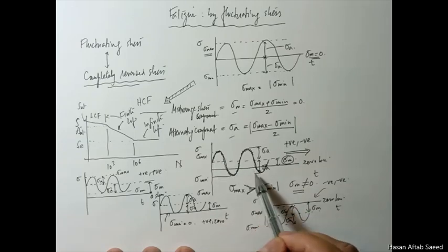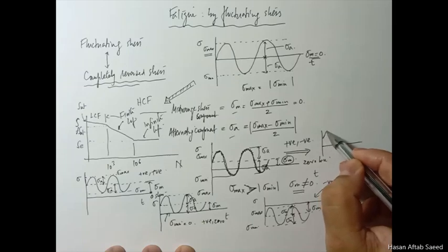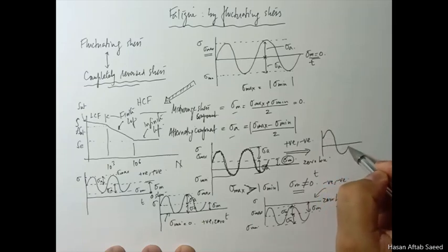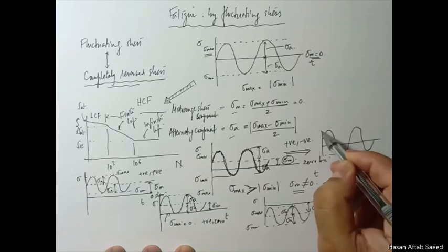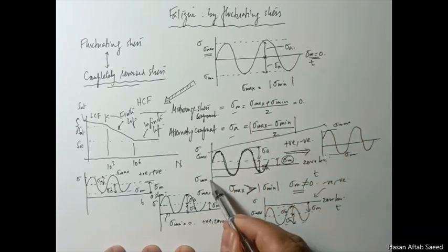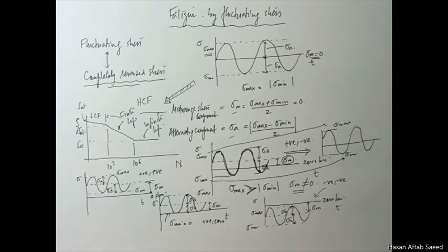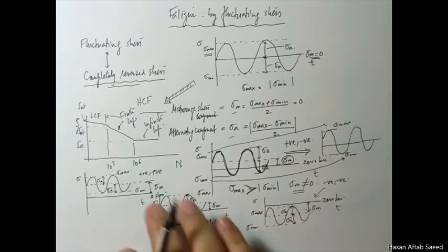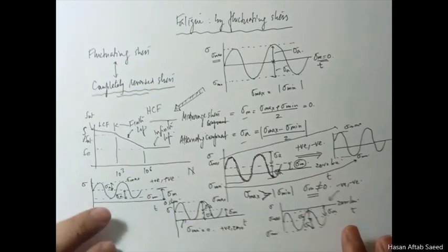Now this sort of thing can very easily be handled by simply taking a simple sinusoidal wave, provided your sigma min and your sigma max are the same as these. So you just ignore these ripples, and experiments bear this out. So you won't be far off in your analysis if you do that.